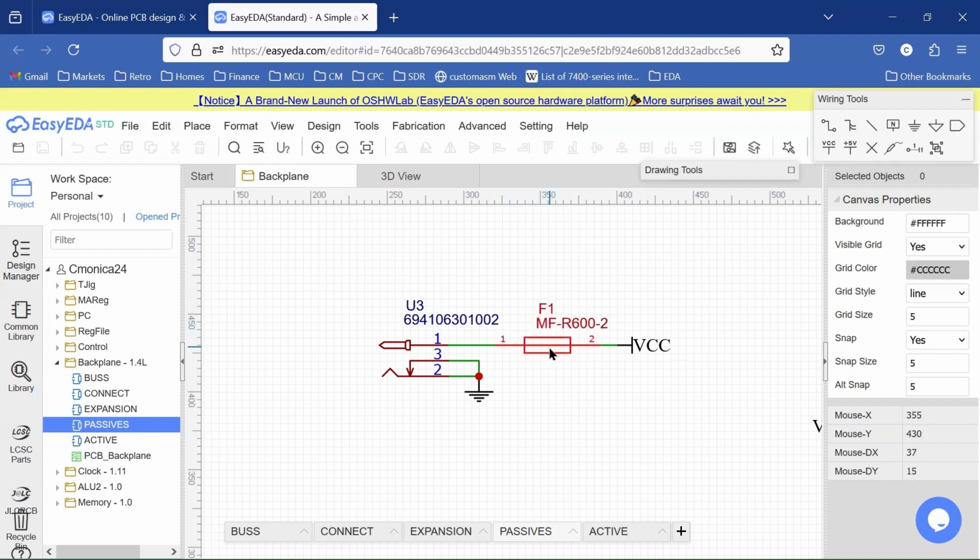And as this heats up, its resistance is going to go down to very nearly zero and is going to be transparent. So this works again opposite from the resettable fuse. The resettable fuse goes up in resistance as the temperature goes up, and the inrush resistor thermistor goes down as the temperature goes up. So now we have a problem.